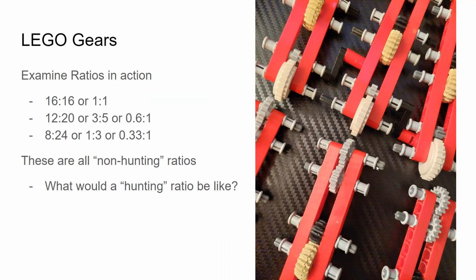You could put it on that axle shaft and spin this gear, and this was a driving gear, and this would be the driven gear. A very subtle difference in terms of those gears. But since they're both 16 teeth, every turn you give this axle shaft results in one turn on that axle shaft. That's pretty straightforward, right? So one turn to one turn, that'd be a 1-to-1 ratio. That's what we got going on the top here.